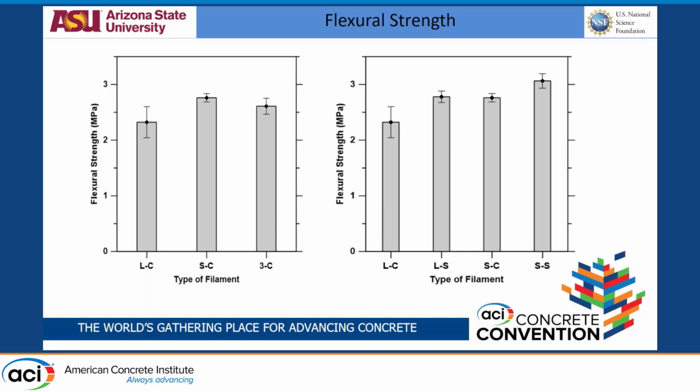So keep in mind that this is the same mixture. When you add steel fiber, yes, there's a steel fiber, but when you don't add it, it's the same mixture. It takes the same amount of time to print the same volume. It's the same print speed. Everything is constant: the filament width, the filament layer height, everything. The layer height is 10 mm and the width is 20 mm.